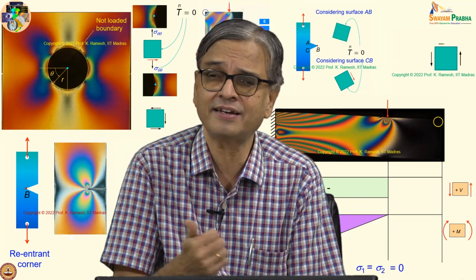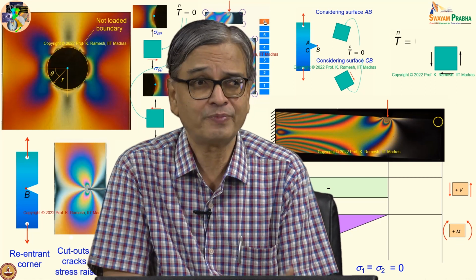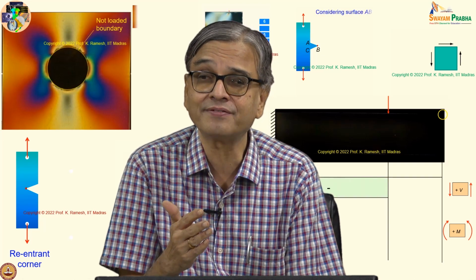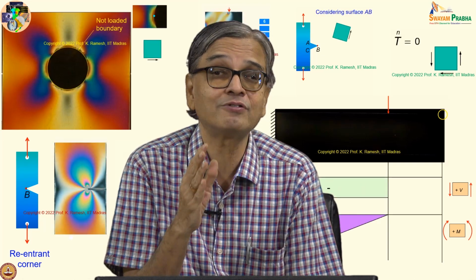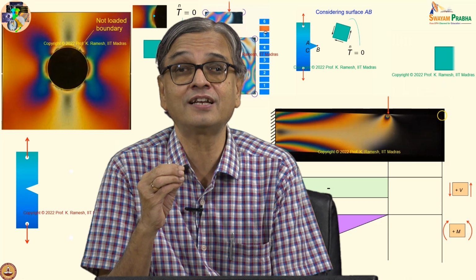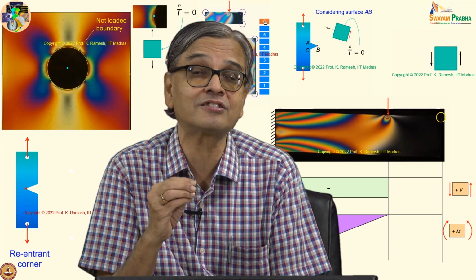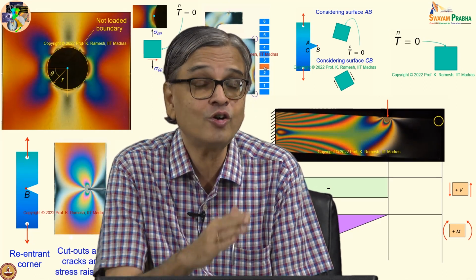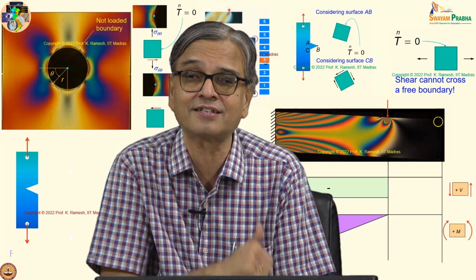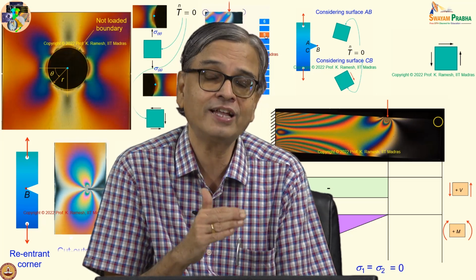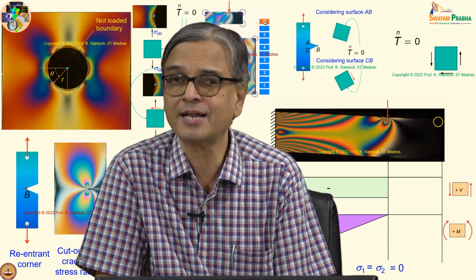Even a scent spray is pressurized. So there are many applications, and you find in that both the principal stresses are positive, and you have to be very careful about sigma 3 being 0. Using that only you should find out the maximum shear stress. Whether it is a local maximum or global maximum in the shear stress value becomes very important in a day-to-day problem. It is not an exotic problem somewhere in your space structure where you have to apply your ultra-modern theory. Not like that. Even in day-to-day structures, you have to understand the concepts clearly and apply them. Thank you.